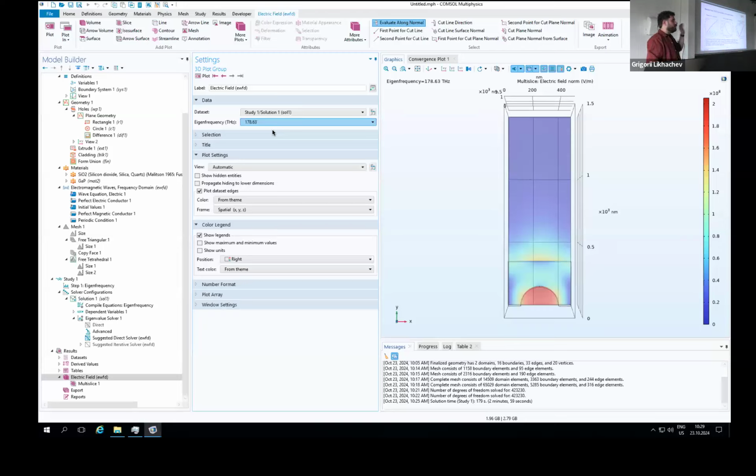But this is actually a good solution if you have a high index material, like here we had gallium phosphide. Silicon nitride doesn't seem to be the best candidate for this because the refractive index is not high enough to be able to get a good reflectivity with few unit cells. So it gets a bit bulky. Still, they proved that with non-chirped mirrors, they can get results quite close to the ring resonators. So that's still good, but I would support these applications more for III-V materials with high refractive index. This is it.